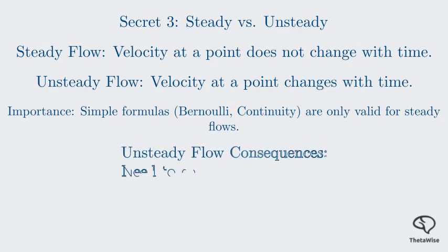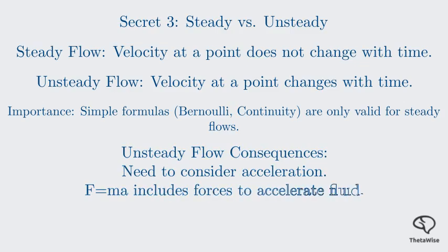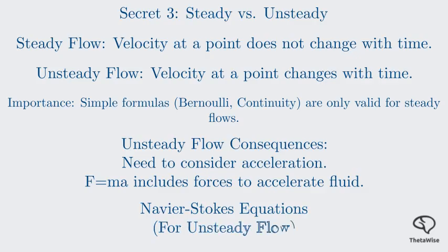F equals ma is still true, but now it's not just the force from pressure gradients. It's also the force needed to accelerate the fluid. This introduces a whole new set of terms. For unsteady flows, we need the full Navier-Stokes equations, which are much more complex. The secret is to recognize when you're in unsteady territory, so you know you need to think beyond the basics.